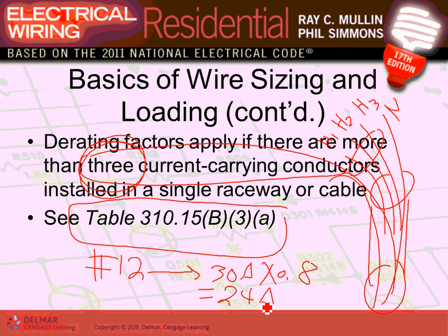The reason why we talk about carrying current, guys, is because if it's carrying current, it's heating. It creates heat. So you're creating more heat. The idea behind you derate if your conductors are more than 3, because if it's more than 3, you have more heat. What's wrong with heat, Chad? Heat will deteriorate the insulation of your conductors. Who cares? If you don't care about your insulation deteriorating inside that conduit and melting, you almost can smell them, and then shorts, then your power is down. If you don't care about that, then don't worry about the rating. That's what I tell the people when we do training for electricians and so forth. So you have to derate. It's the law. Any comments, guys, about derating the conductors based on bundling?